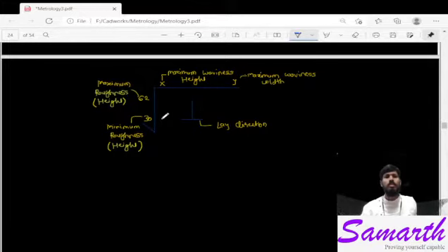Both of these are heights, whereas on the horizontal surface at the top there will be the waviness value, the maximum waviness width, also called the maximum waviness spacing. And this is the symbol of lay, the lay direction. It may be different.